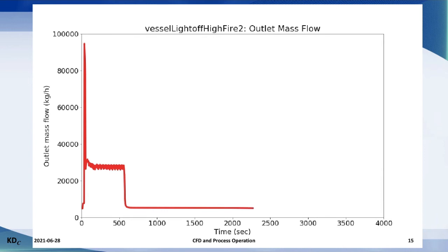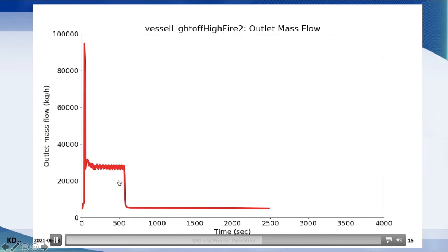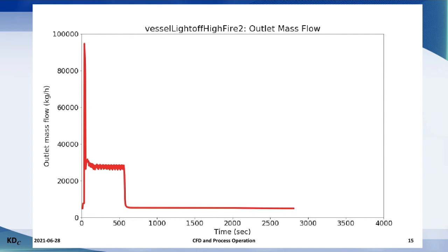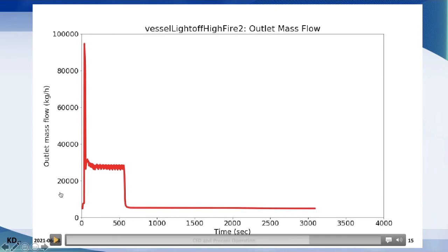Now keep in mind, this represents a large flow disturbance. An additional 60 cubic meters an hour going to our online bed, which took a raw feed of 100 cubic meters an hour, is a really large disturbance. So taking almost double the flow rate, or worse yet, this super high short-term spike of liquid that is approaching 200 cubic meters an hour, that would be an intolerable change in flow rate through that molecular sieve bed.